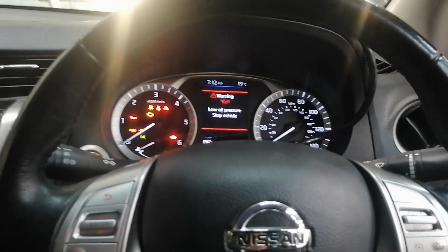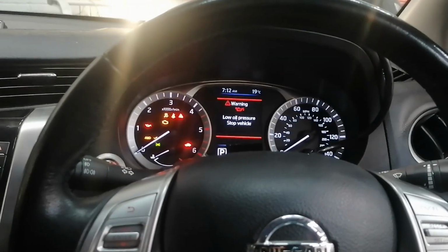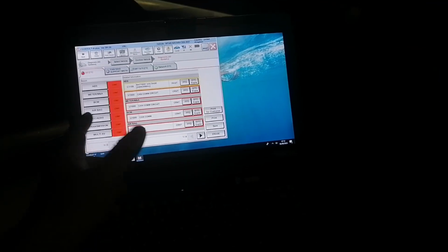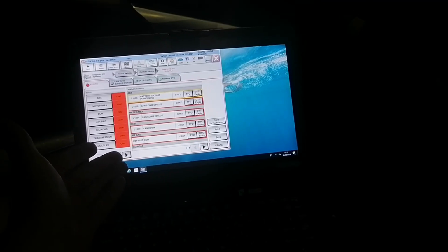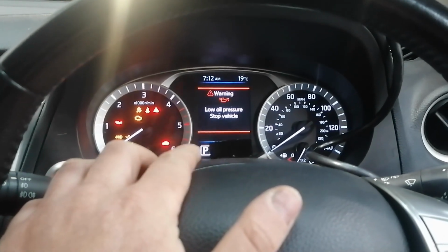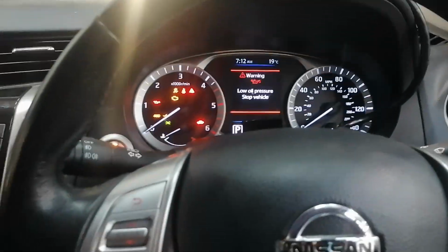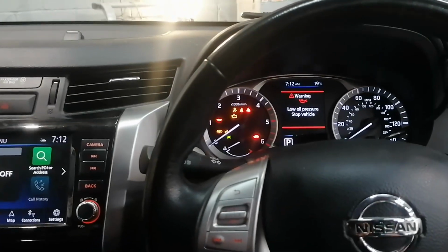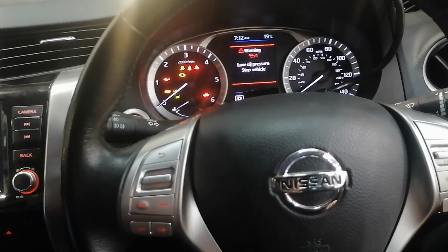A little bit about what we can see at the moment and what we have. So this looks like a module offline, and obviously our list of DTCs confirms that. So we do have the engine control module offline. I know for a fact that this happens when you reflash the engine control module. For those who don't know, when you do a remap, or not a remap, a reflash, there is a specific time that the engine module goes offline to rewrite the new software, and